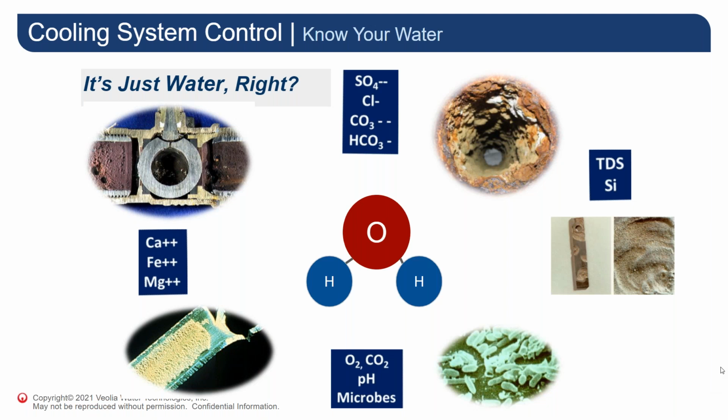Dissolved gases such as oxygen and carbon dioxide can also complicate water efficiencies and alter water pH, which can influence the scaling or corrosive nature of the water, as well as contributing to accelerated pitting corrosion, which can burrow through standard piping and equipment very, very quickly.